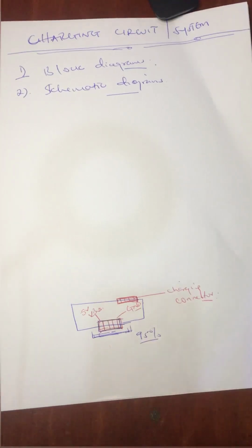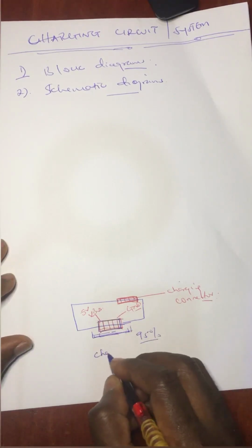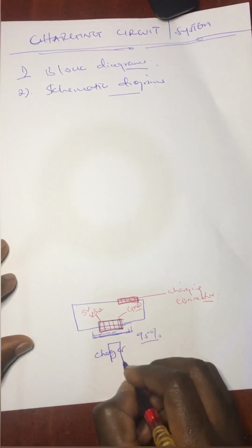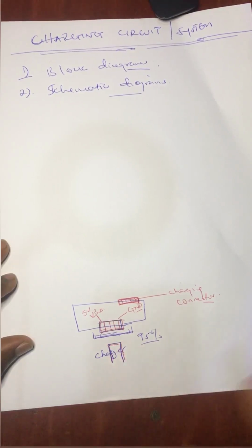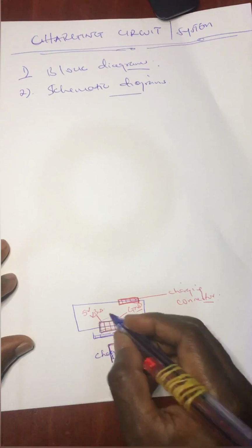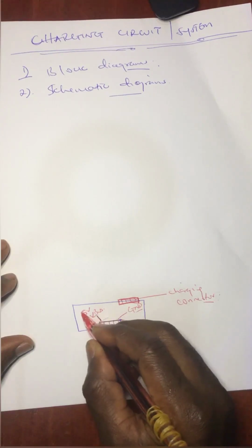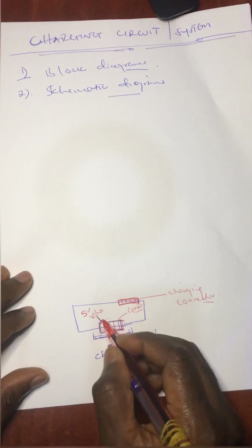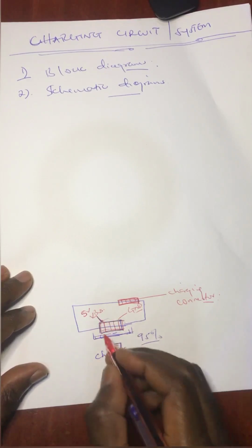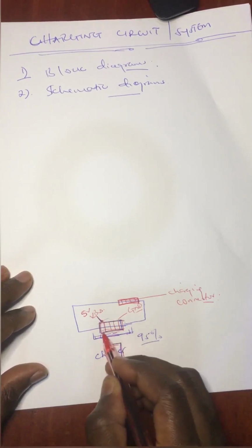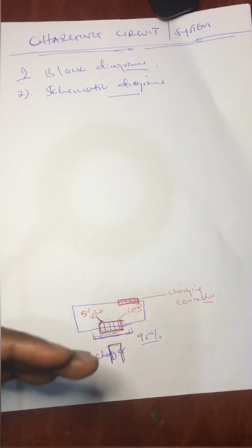So this is the basic functioning of the charging system. When you connect the charger on the charging connector, it brings in 5 volts. If you use your multimeter to test on the charging connector, you'll have your 5 volts right here. The moment you have 5 volts right here, it means your charging connector together with the charger are working. So where else do you go after this?